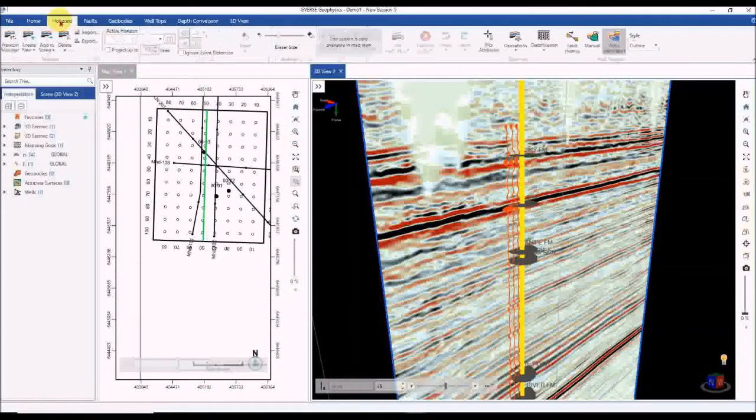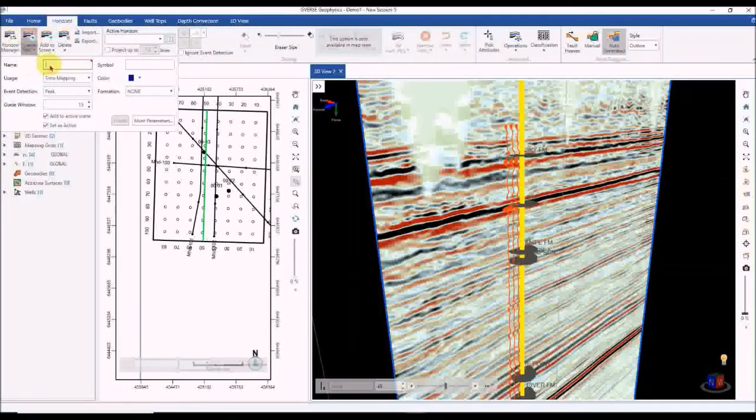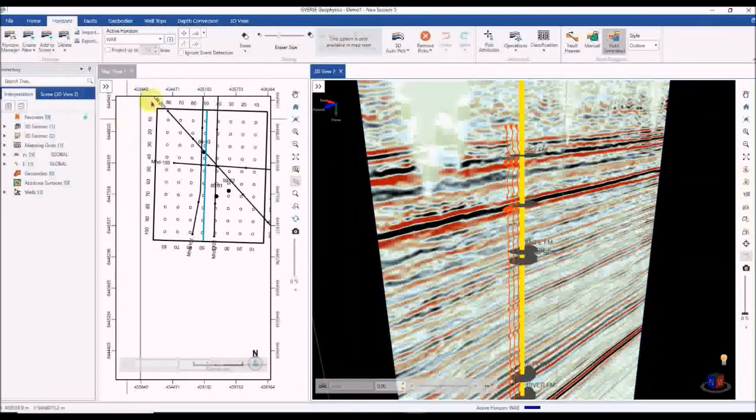view. So the first thing we need to do is go to the Horizon tab and create new. Let's say we're going to use WAB as the name for our horizon, and we're going to do a depth conversion as the end workflow. We will have our data in depth. And here's a new addition to attach right here to our formation, and when we create it, now we have that in, and it's already active here.